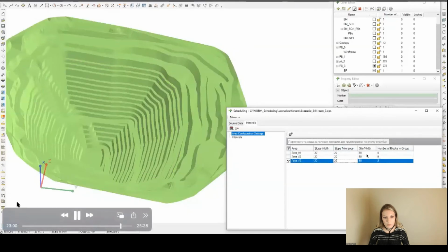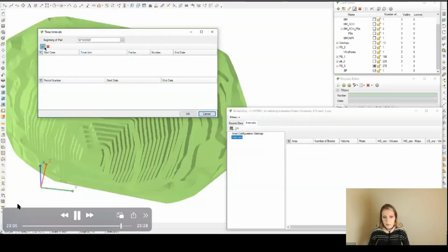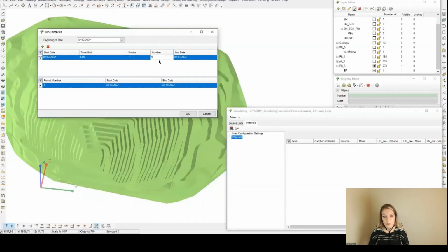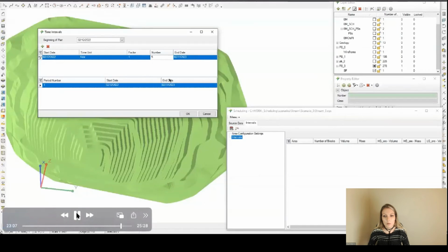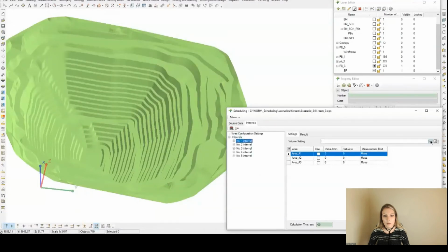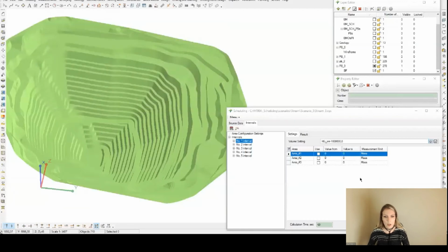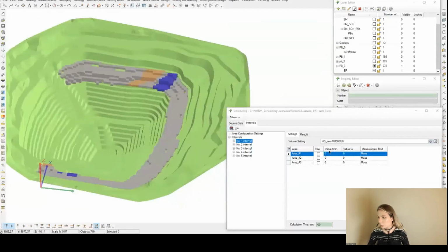We set the parameters to configure sections and intervals. And in the current scenario, we specify the high-grade ore target as 1.8 million tons and rock transportation of up to 9 million tons for the period. And now we're going to see how to search for the result using another target indicator, which is waste transportation. And we're going to set it as 8 million with a high deviation rate, so we would not prevent the search algorithm.